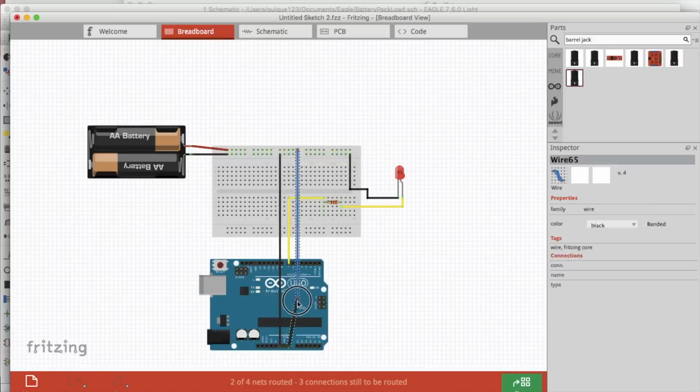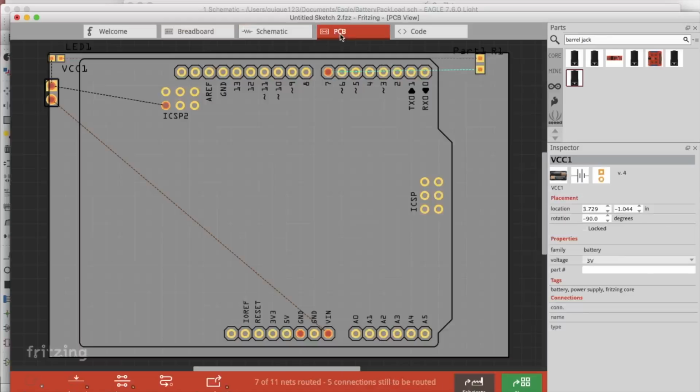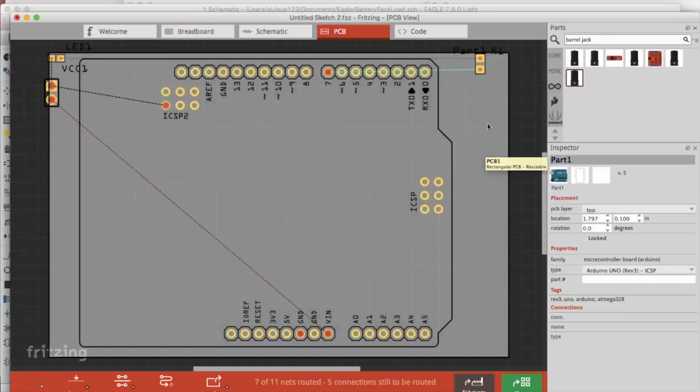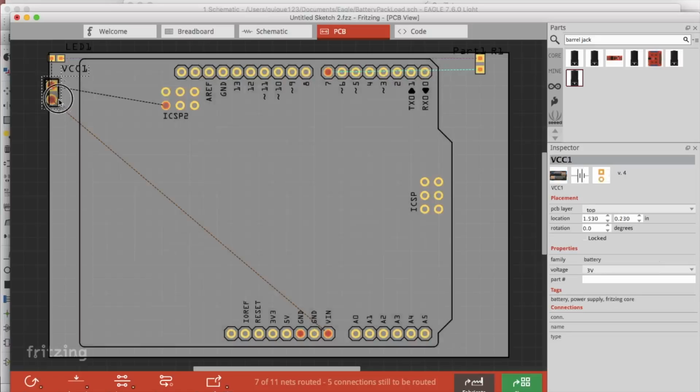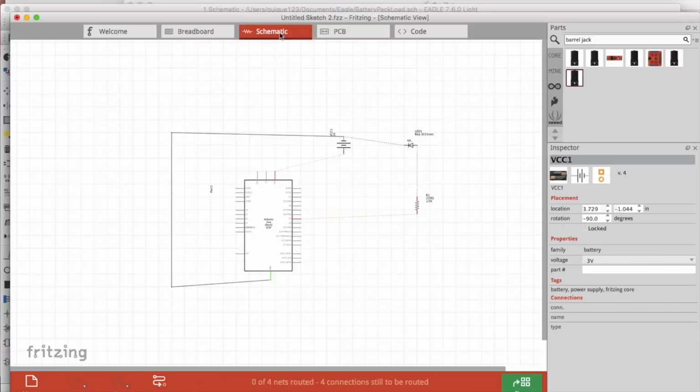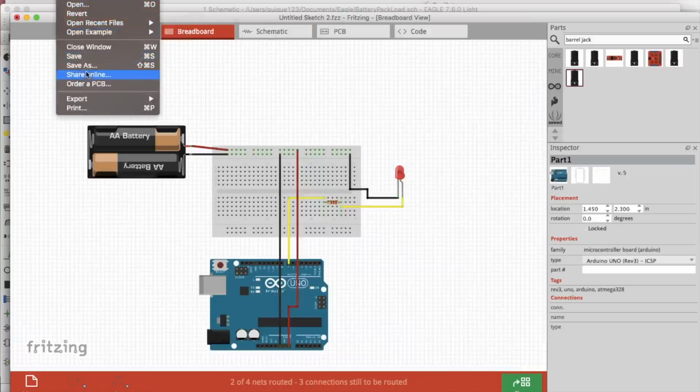So when you design a PCB, paths have to be really close to each other, they have to be tight, they have to be very precise and even in thickness to account for the current that's going to be running through it. So as you can see here, you can move components around, but until that dotted line becomes a solid line, that is not where the connection is going to go through. So there is an electrical connection between those components, but the actual trace is not really there yet. Okay, so let's go ahead and save this and move on.